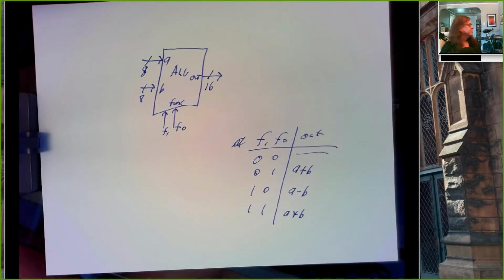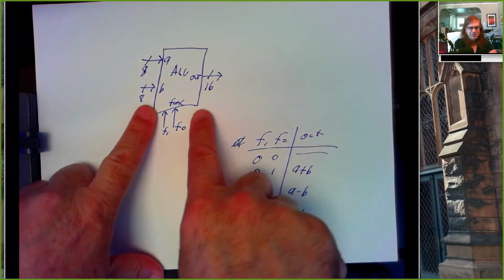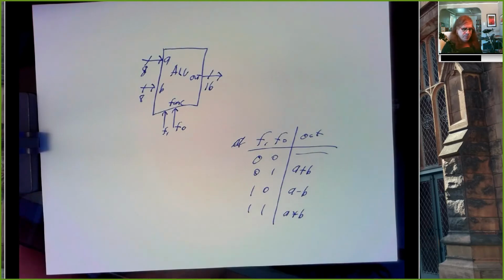And go ahead. Types where it's like more than 8 inputs, right? Or more than 8-bit inputs, right? What was the start of your question? You can have an ALU with way more input bits, right? Okay. Definitely. If you had a 64-bit CPU, you'd want a 64-bit ALU. But there's a really popular chip that's a 4-bit ALU. And a lot of these larger ones are built by just taking those 4-bit ones and putting them together.